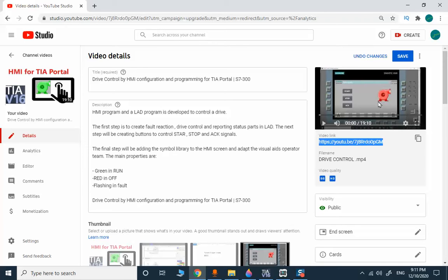In this topic, we will encapsulate all of these commands in a faceplate. A faceplate makes commands for similar devices reusable at the HMI level for several cases in the same project or for future projects.